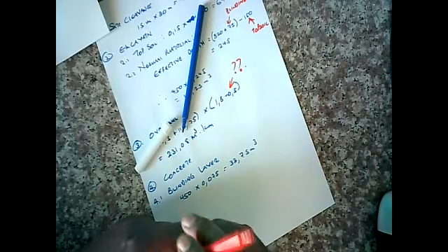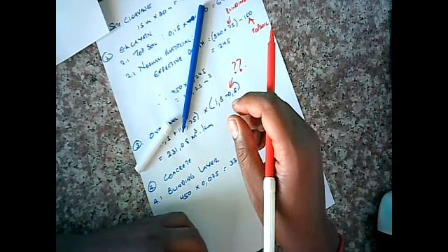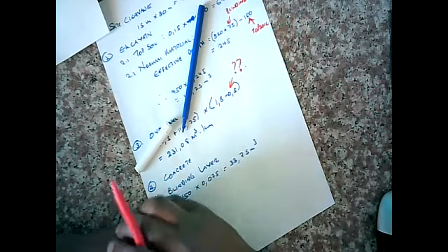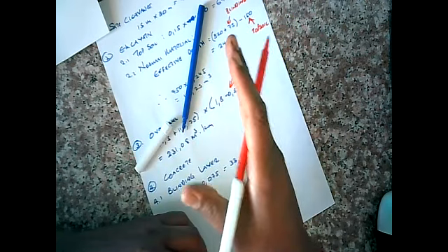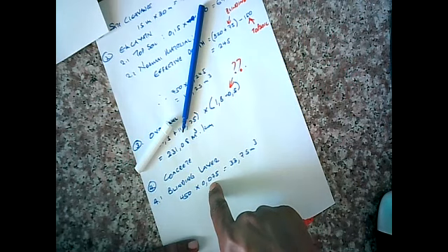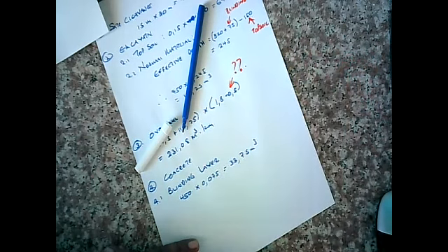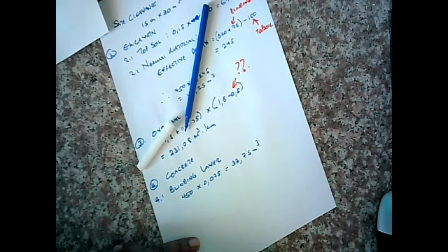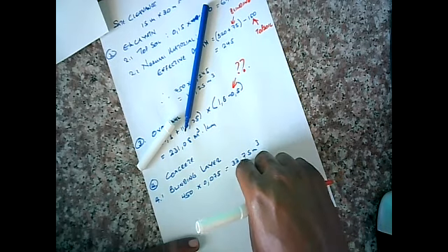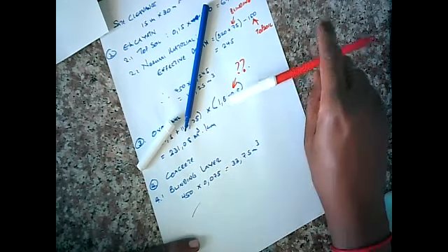All right, now please don't make this mistake, and I've seen it regularly. 100 millimeters is 0.1. Anything below the 100 millimeters, there's an extra 0. This is 75. There's the extra 0 there. Now, don't, in your haste, do 75 divided by I don't know what, and you get 0.75. 0.75 is 3/4 of a whole meter. Throws this up considerably, and it's wrong. Okay. Careful for that dimension there.